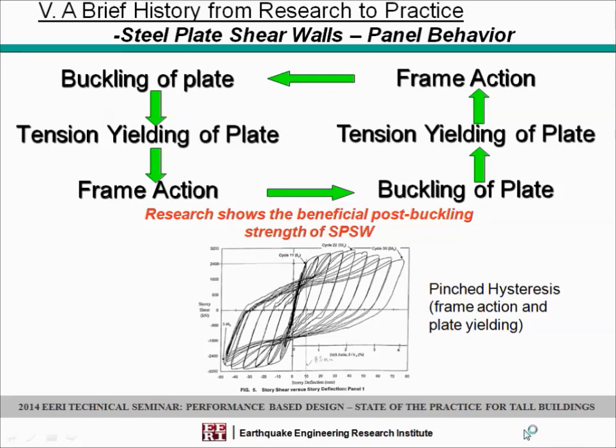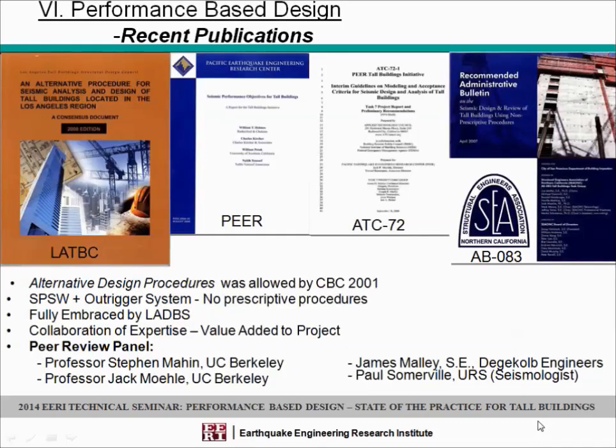And the research has shown the benefits of that post-buckling strength that's still available, and we'll see further on that. It's a pinched hysteresis because of some of the frame action and plate yielding.